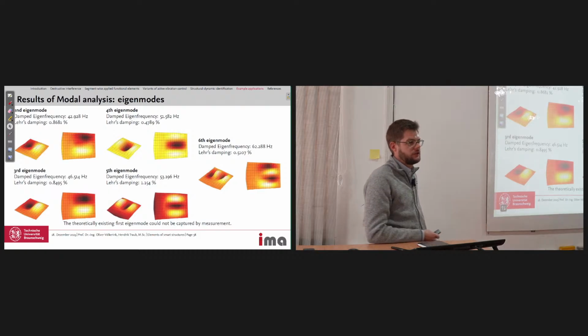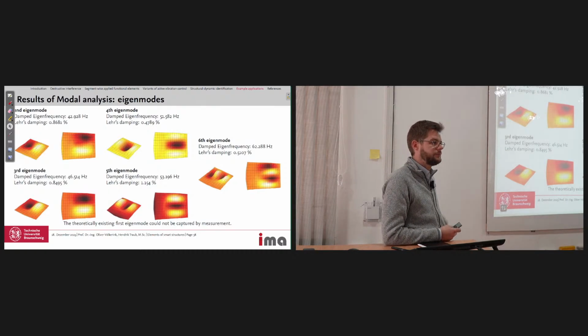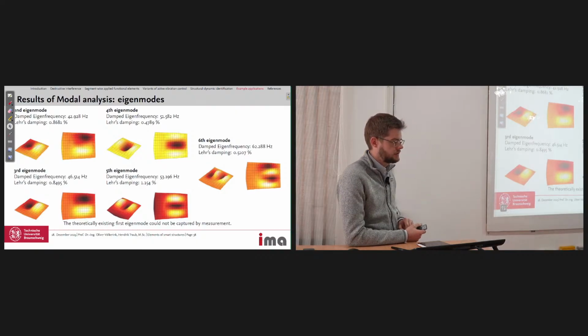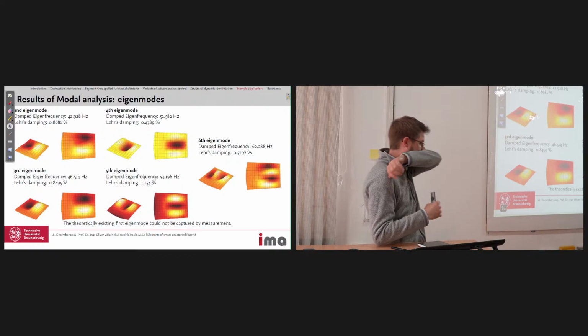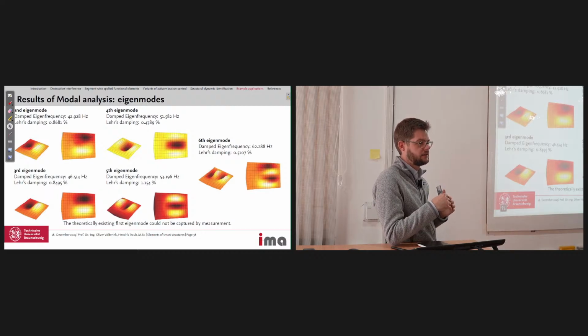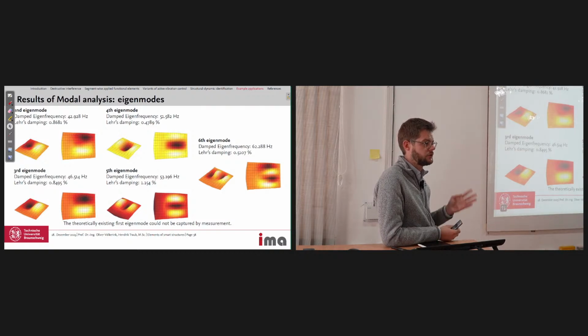Yeah, it would be a structural adhesive, for example. Yeah. We can calculate it, but I think the goal is to have this interface so stiff that it does not influence the transfer of the vibration from the actuator to the structure. So you would not use some kind of very elastic adhesive, but a rather stiff one that you can transfer really the vibrations without changing the behavior.